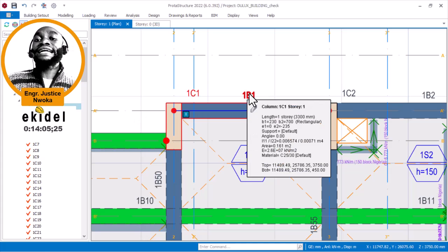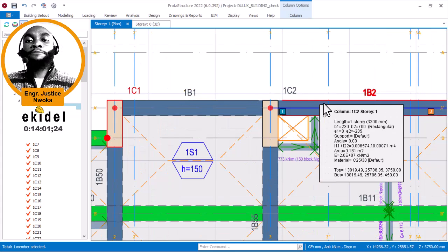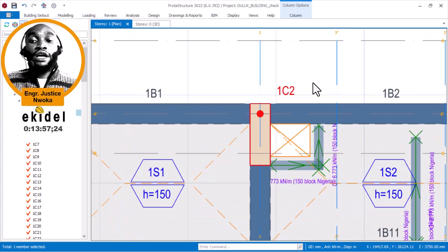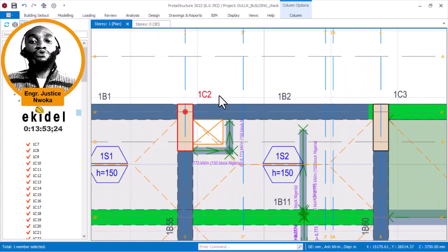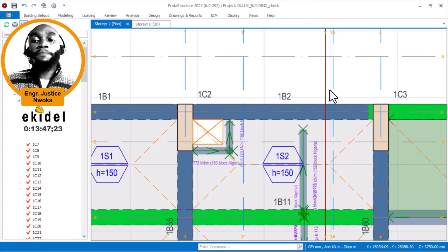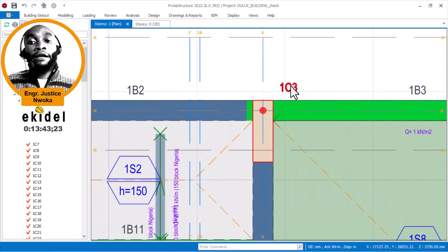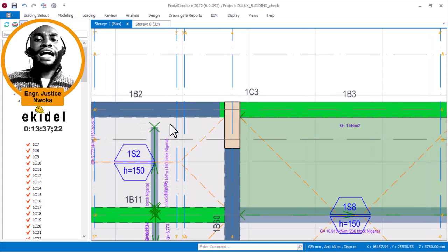Okay, so this is an end to this beam 1, and for this mid span for this continuous beam, after this column 2, which is C2, there is still a continuous beam which is beam 2. So this place right now becomes a fixed end. Okay, so I'll skip this place from hinging, and then if you come here again after the beam 2, after this column 3 here, there is still a continuity on the beam which is now beam 3.